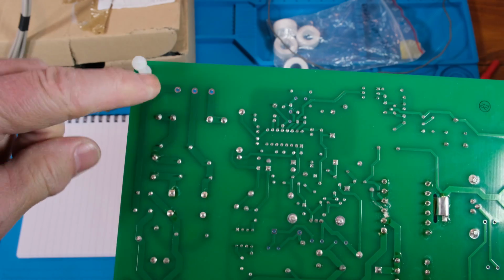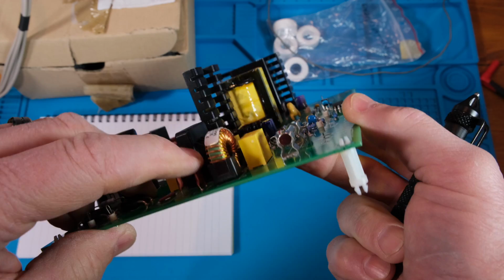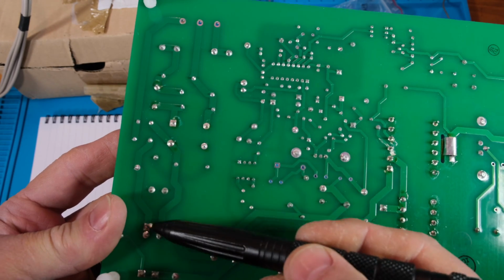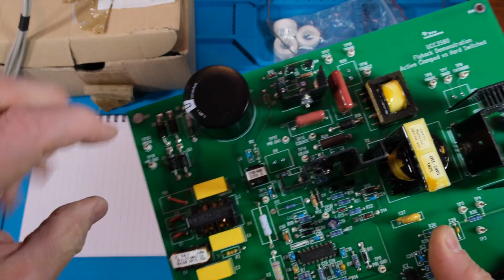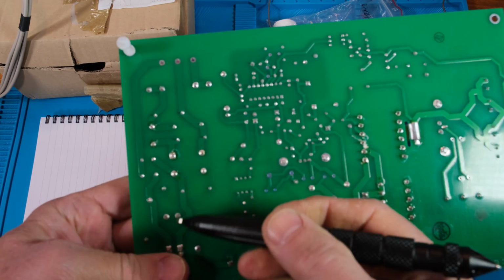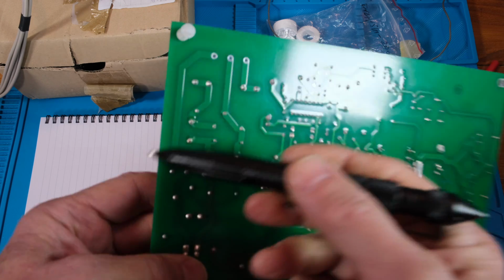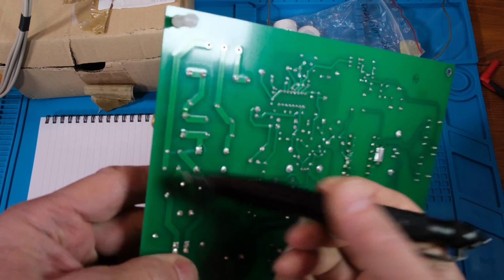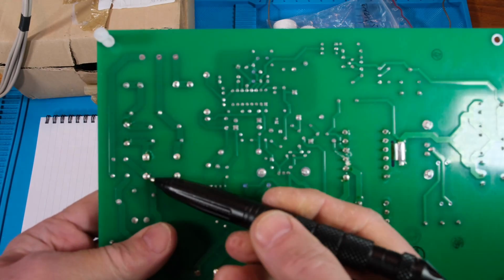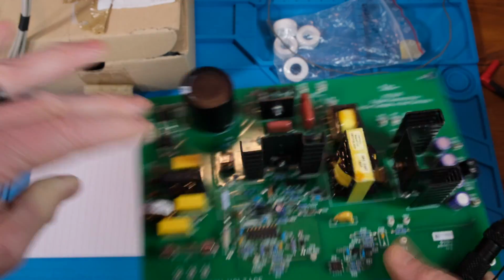Okay. Now, ground comes down here to these two pads. And then look, one of the Y2 caps right here goes to this. And then the other one goes to this guy. So, right here off the rectifiers, we have our Y caps. Okay. So the rectifier comes over here. Right to this one, to that Y cap, and up here to this one, to that Y cap. And then our common mode choke right here, okay? So then our common mode choke's right here. So the Y caps are on the rectifier side of the common mode choke.